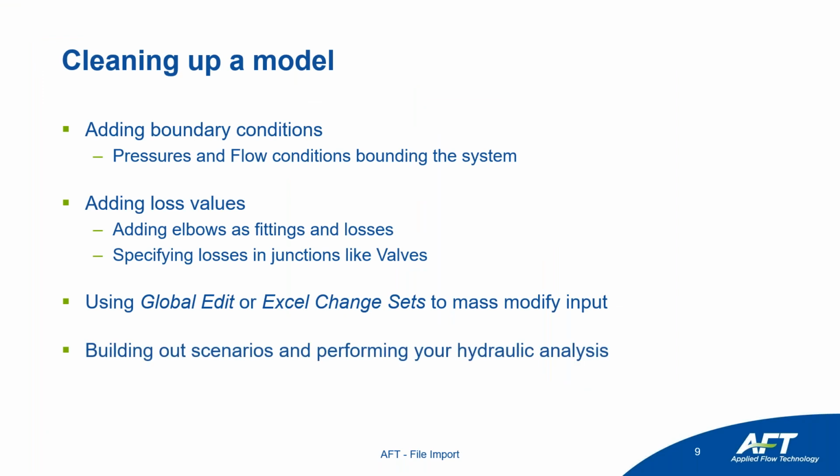So to kind of recap, with importing, this is really just the first step in building out your hydraulic analysis. We have all of our pipe lengths, diameters, elevations, but we also want to, again, define those boundary conditions, add losses, and then finally start building out our different scenarios. And then performing that hydraulic analysis, that has its own rules, which if you're interested in these webinars, we have plenty of other webinars that can walk you through that process. So this is just the first step. Again, you want to make sure your input's very good and don't build your model on top of bad input, making poor assumptions.